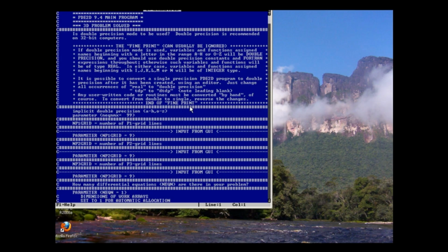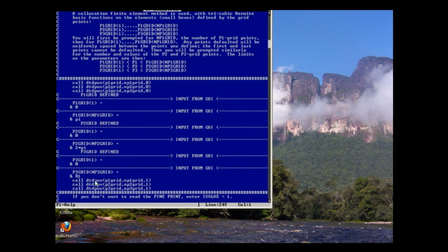The parameters you defined during the GUI session appeared here. For example, here we asked for a 9 by 9 by 9 finite element grid. Lines that are lowercase normally should not be touched by the editor. Uppercase is normally input from the GUI. You can modify the grid now as documented above in the comments. For example, it explains how you can easily make the grid non-uniform now.